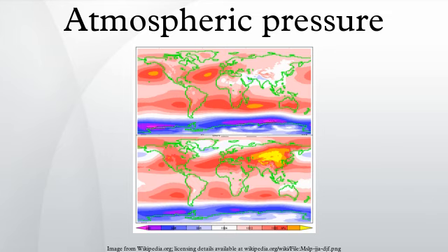Average sea level pressure is 101.325 kilopascals or 29.92 inches or 760 millimeters of mercury. In aviation weather reports, QNH is transmitted around the world in millibars or hectopascals, except in the United States, Canada, and Colombia where it is reported in inches of mercury. In the weather code, 3 digits are all that is needed. Decimal points and the 1 or 2 most significant digits are omitted.